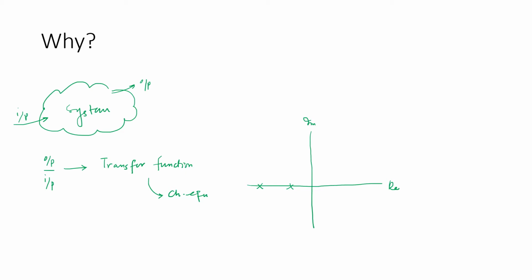And that is going to be an important aspect to be considered in order to understand the stability and behavioral analysis. So on the left side, you are going to have the stable region, and on the right hand side, you're going to have the unstable region. And that is when you plot the characteristic equation or roots of the characteristic equation on an S-plane.